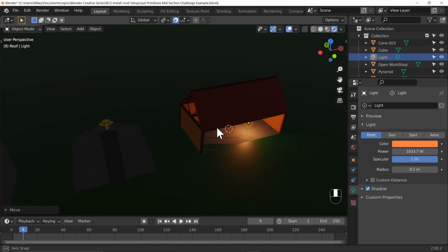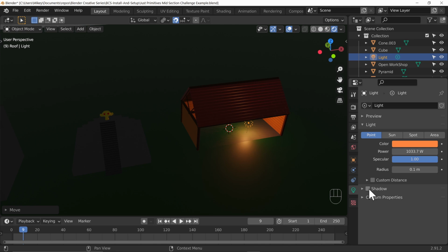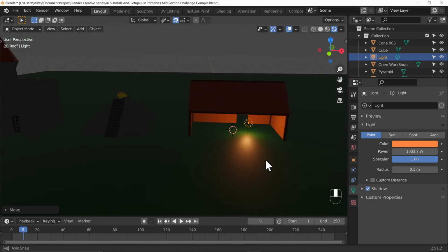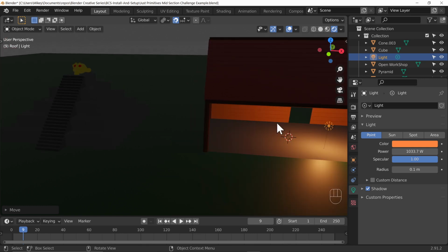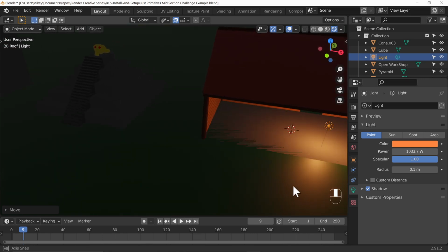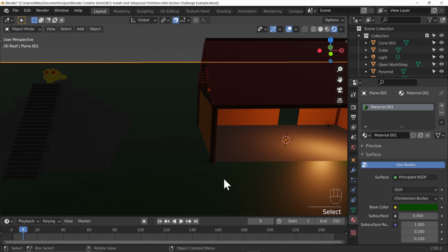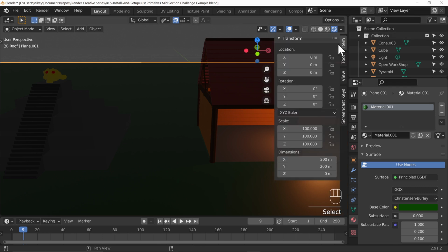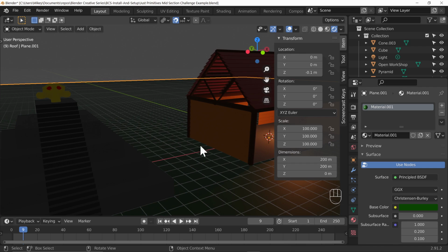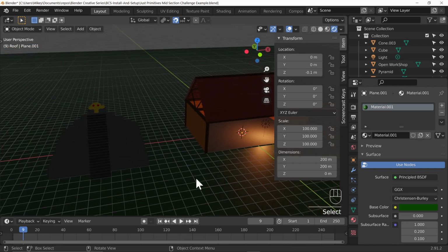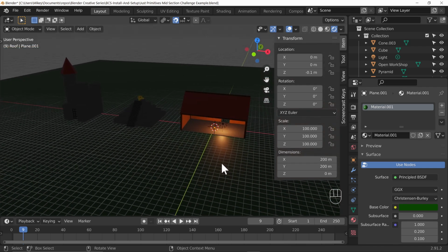One of the things that you can do with Eevee is turn off whether or not a light will cast shadows. Oh, and whilst we're here, can you see the Z fighting that's happening with the coplanar face? I don't like the look of that. I'm going to grab the ground plane and adjust its location in our world by -0.1. Then it will be slightly below, and all of our objects will be slightly floating, but I will let that slide for the moment.